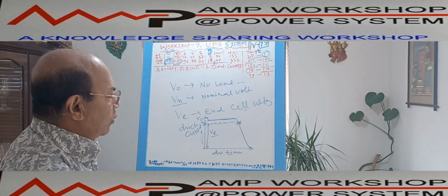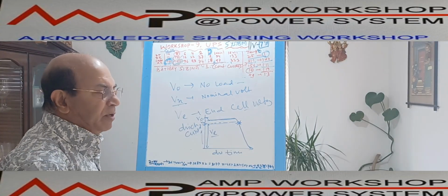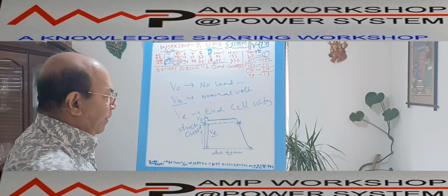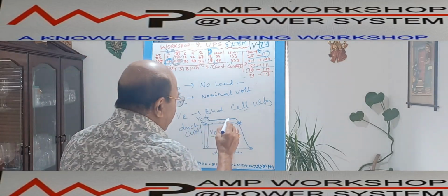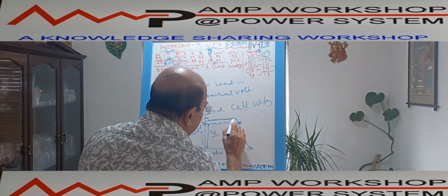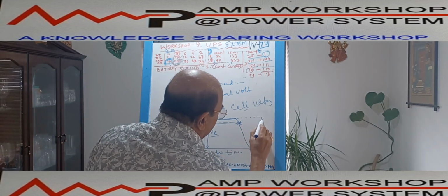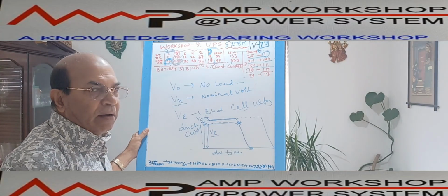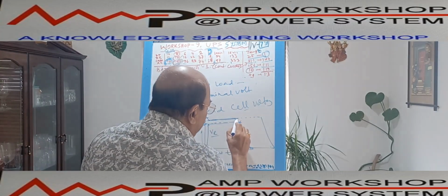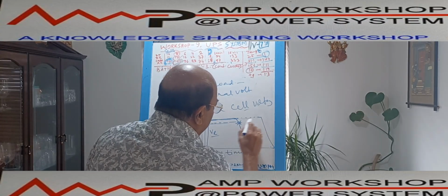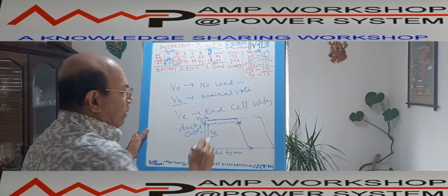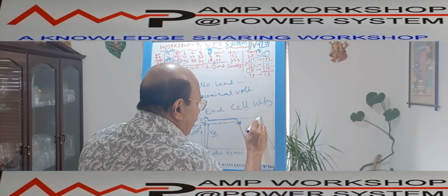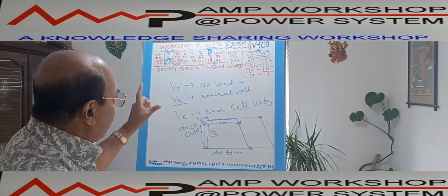So these are the three voltages of a cell. We have discussed two types of battery: the lead acid battery and the nickel cadmium battery. In the case of the nickel cadmium battery, the advantage is this constant voltage discharging; it goes further and then drops. If a load is so sensitive that it cannot take the voltage drop, then we have to go for the nickel cadmium battery, because it can deliver for a longer time with constant current delivery, or constant voltage, during discharging. The battery terminal voltage can be maintained for a longer time. So these are the four parameters.